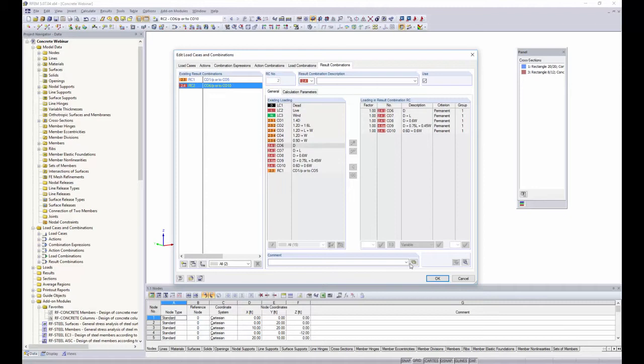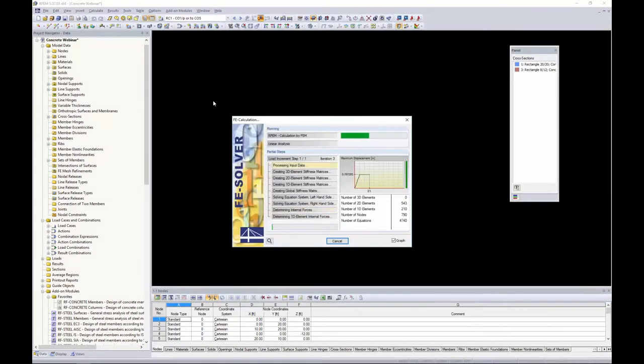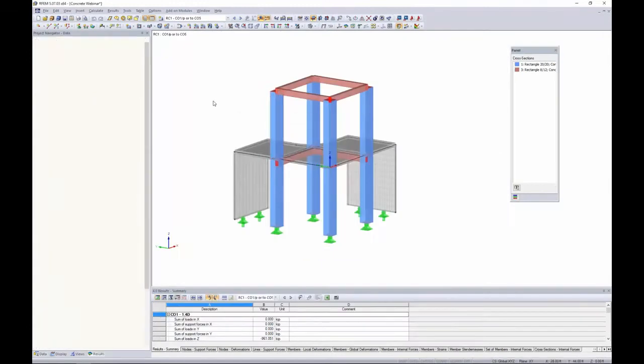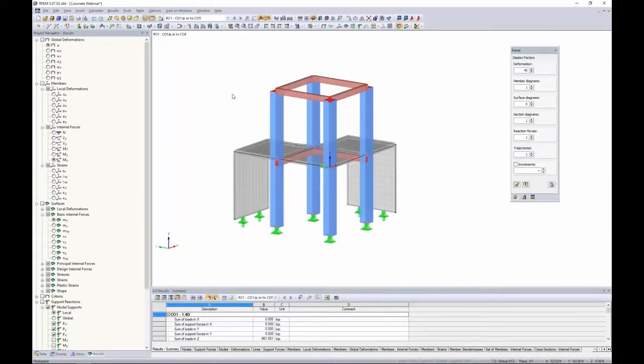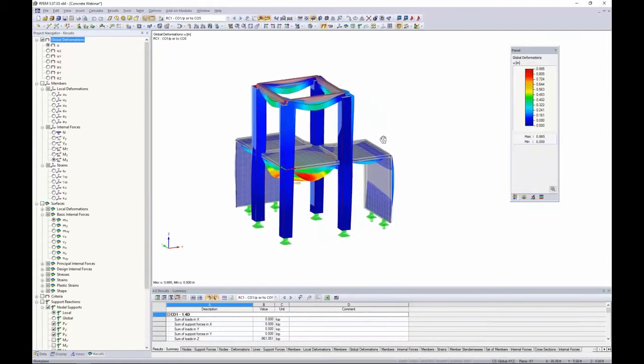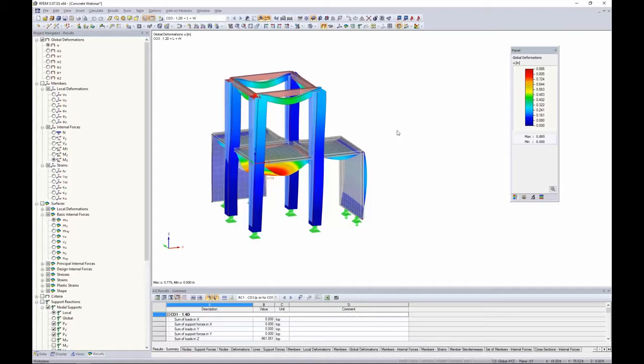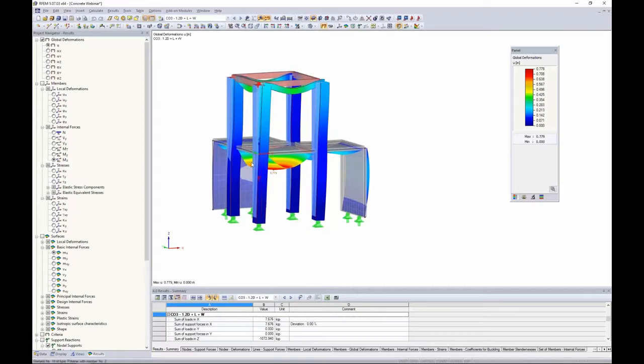And with that said, we can go ahead and run our first analysis with our result combination 1. And you'll notice that this is nonlinear analysis. As I was saying, it's P-delta. It solves rather quickly, and we are given the envelope solution for all of our LRFD equations. Maybe I want to jump to something more like load combination 3 here, 1.2 dead plus live plus wind. We can see our deflection is given at 0.779 for our slabs. We have deflections of our members.